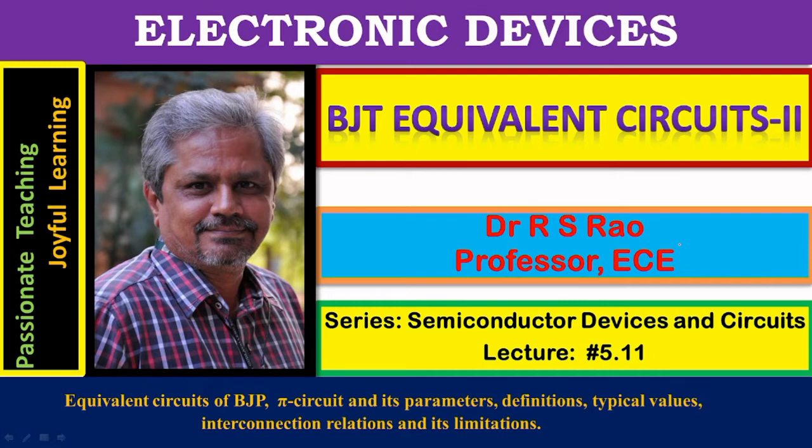Electronic Devices, BJT equivalent circuits, Part 2, Series on Semiconductor Devices and Circuits, lecture number 5.11. BJTs are basically associated with 2 equivalent circuits. One is the H parameter equivalent circuit, another is the pi equivalent circuit. The first one is a low frequency equivalent circuit, whereas the second one is a high frequency equivalent circuit.